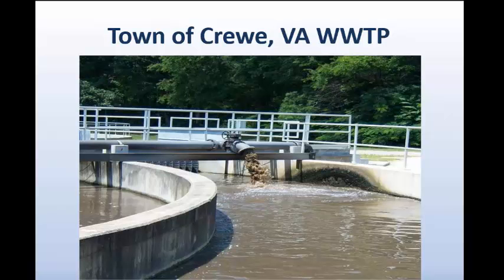And then in addition, the plant was designed originally so that at the influent, the water coming into the plant, it goes through a grit removal process where the heavier solids settle out. And in part, to accomplish this, it went through an aeration channel. That was also imparting dissolved oxygen into the waste stream.